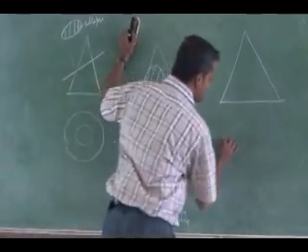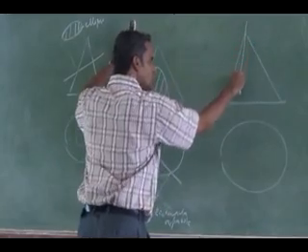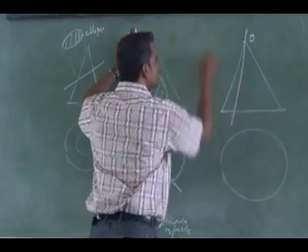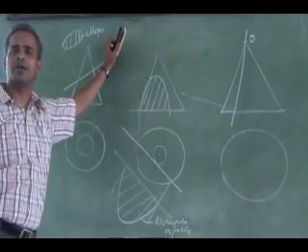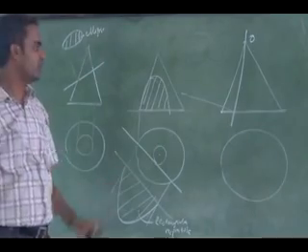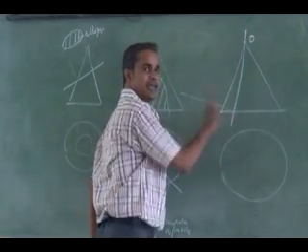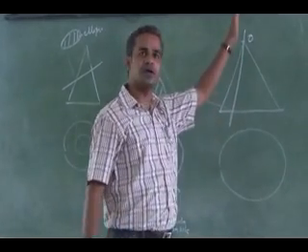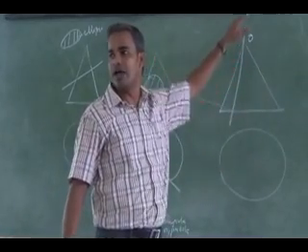Suppose I have a cone like this. Already you know, if I am cutting the cone passing through its apex, what will be my true shape? First of all, tell me how many cutting points I will get for this. Three cutting points. It goes through the apex, so there I will have one cutting point, and it cuts the base at two cutting points. It doesn't cut a generator, because the cutting plane itself is aligned with the generator. So totally I will have three cutting points.